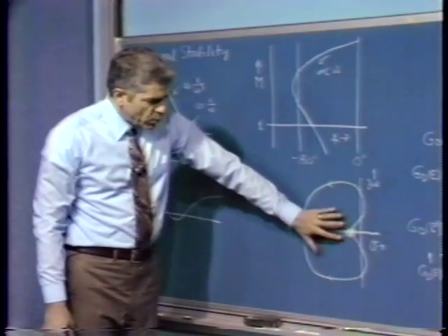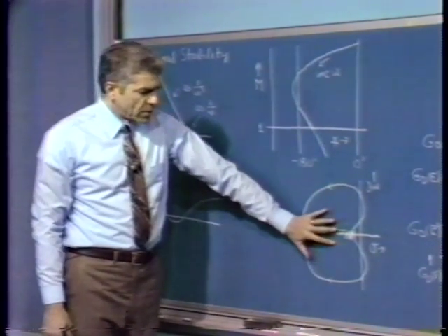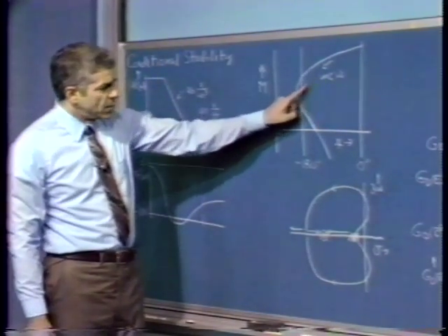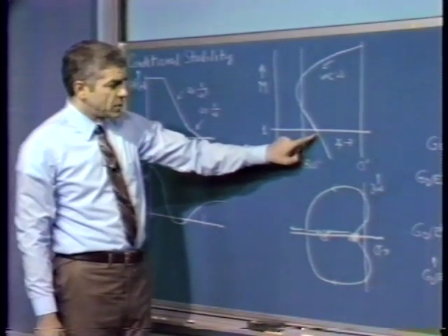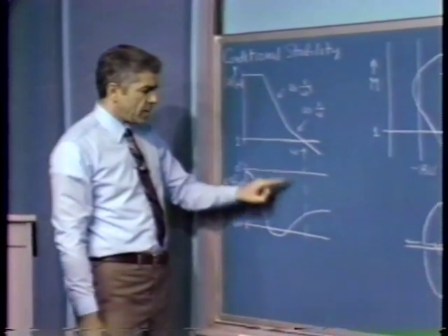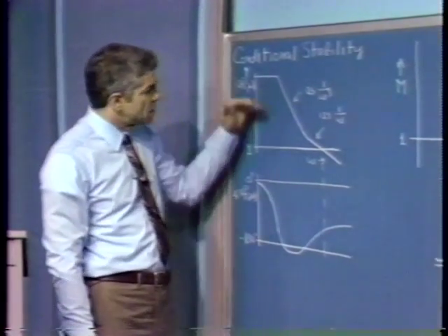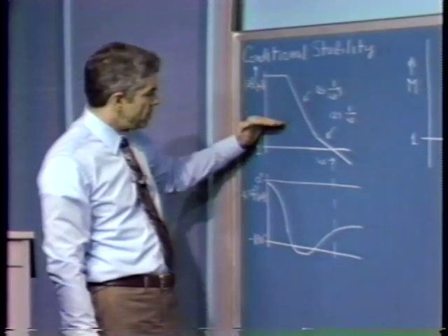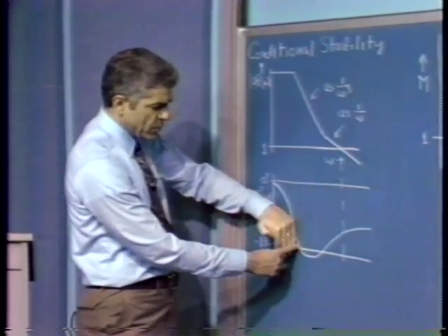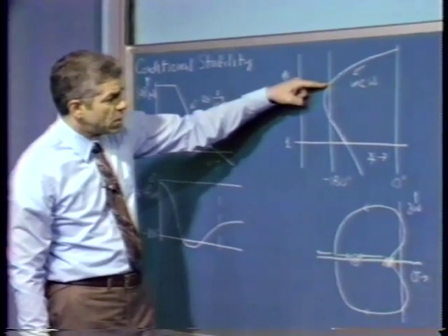The situation with sufficiently large A0 F0 magnitude such that all 3 branches lie in the left half of the S-plane is the situation we've shown in this gain phase plot. We have a stable system with a positive amount of phase margin. And similarly, in the Bode plot, the other stable situation would correspond to the magnitude curve being pushed down so far that system crossover occurred at frequencies below this one, or at frequencies below this one in the gain phase presentation.